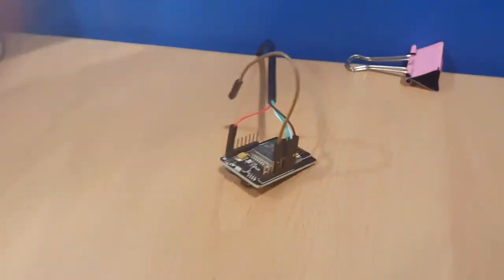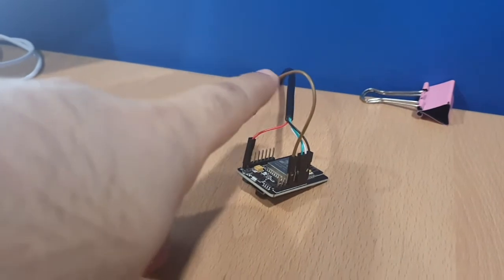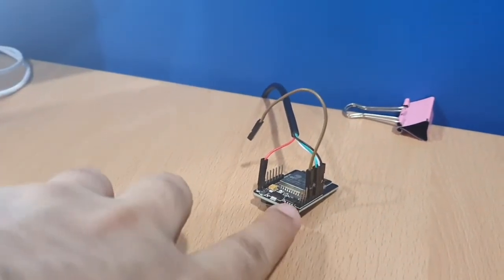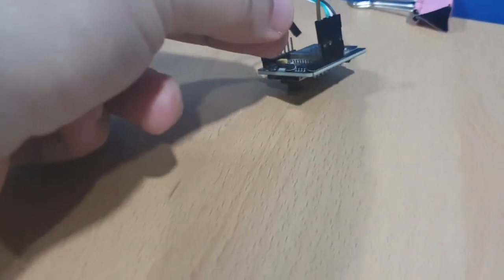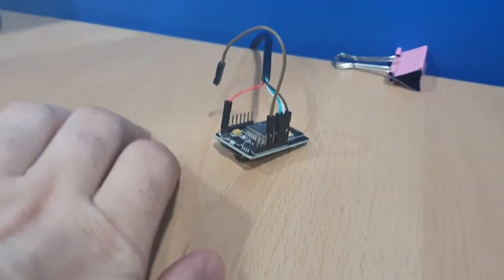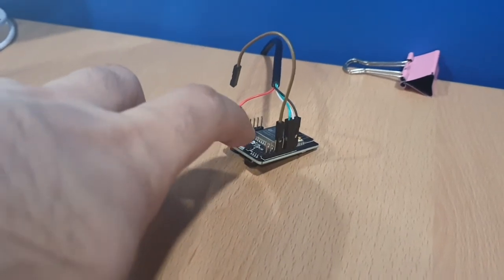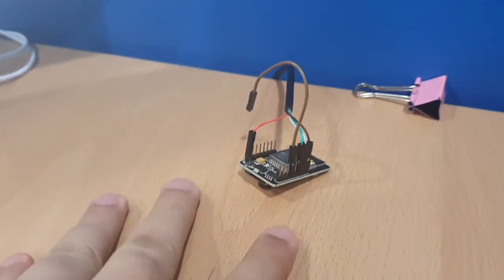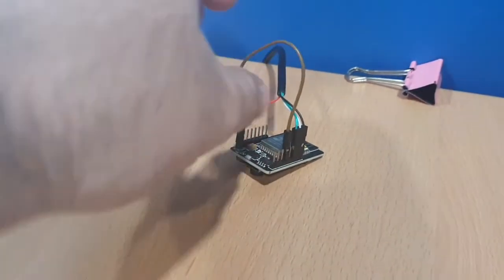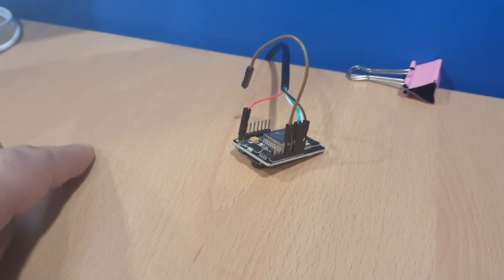So the key thing is that when you are pushing the code from your Arduino IDE to this, you need to connect this ground, shorted out with input 0, which is right next to this ground pin port. The code can be pushed the moment I do that. But every time I need to run my Arduino, now that the sketch is already loaded on it, I need to unplug these two pins, and then it starts to work.